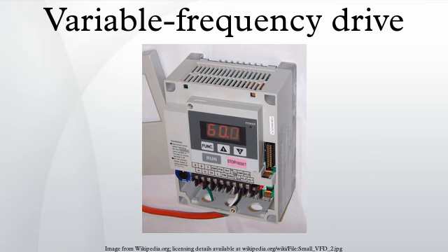Available power ratings. VFDs are available with voltage and current ratings covering a wide range of single-phase and multi-phase AC motors. Low-voltage drives are designed to operate at output voltages equal to or less than 690 V. While motor application LV drives are available in ratings of up to the order of 5 or 6 MW, economic considerations typically favor medium-voltage drives with much lower power ratings.